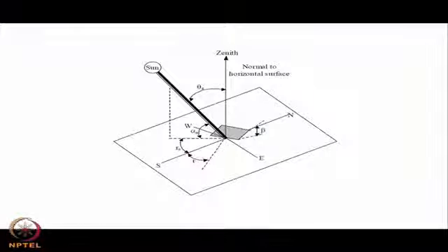Azimuthal angle also towards east is negative, towards west is positive. So, if you go towards north via south, you can have a gamma of plus 180, and if you come the other direction, it will be minus 180. So, in your angles and equations, when it is due north, whether you put gamma plus 180 or minus 180, you should get the same answer.